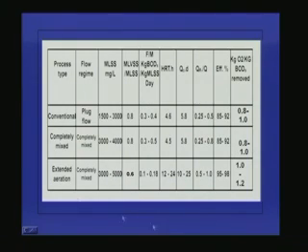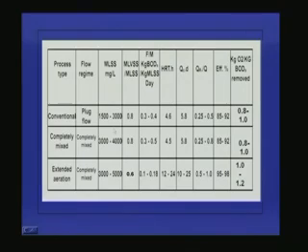Now, we will come to the extended aeration system. The advantage of this system we have already discussed. There is no sludge handling problem because the entire sludge is getting stabilized, or the microorganisms are undergoing auto-oxidation. So, whatever sludge comes out of the extended aeration system is mainly inorganic substances. So, we can directly take that sludge and dispose it into sludge drying beds. Naturally, if you want to completely oxidize the entire organic matter, then the oxygen requirement will be more. So, we will see what the requirements are.